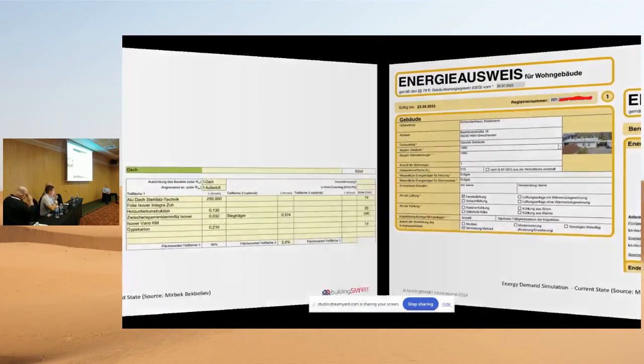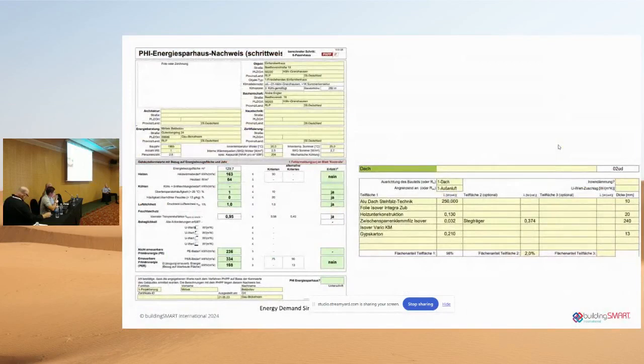Yeah, and now, as you can see, Richard, we improved the roof insulation. We increased the insulation from 100 millimeters to 240 millimeters. We also applied an intelligent, continuous air tightness barrier. The contractor was really helpful.